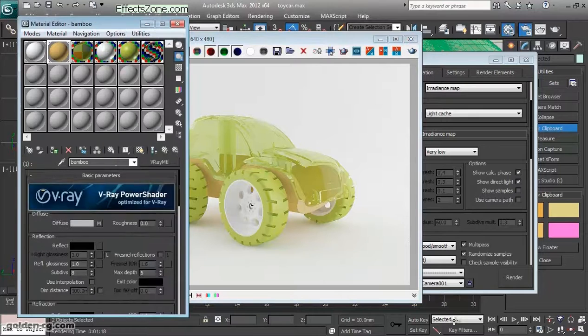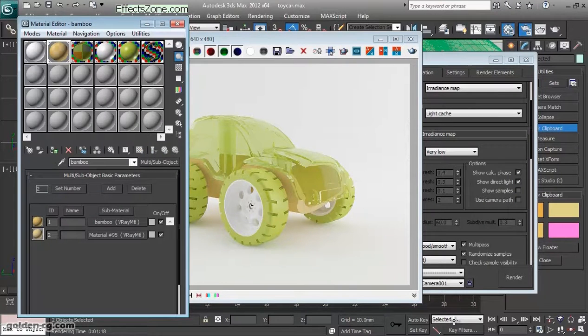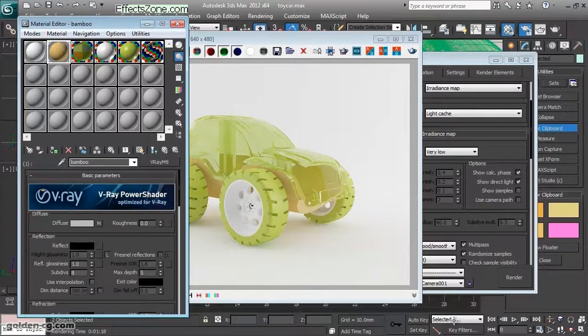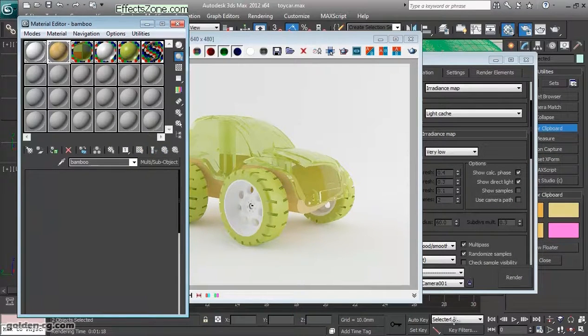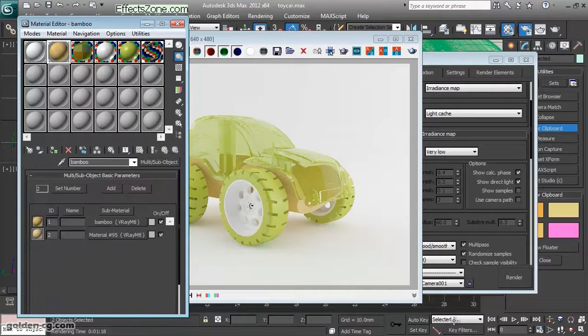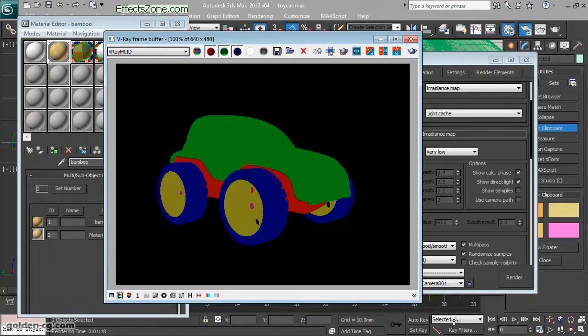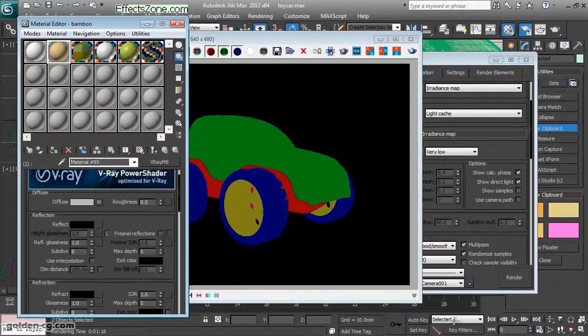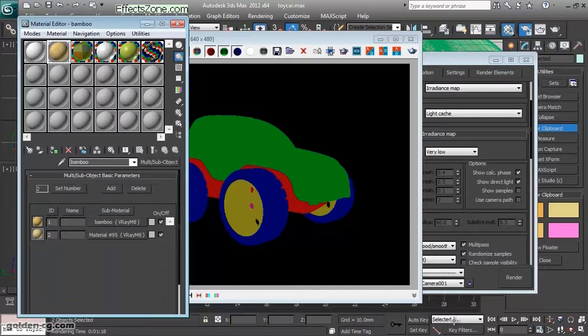And one note, I just changed it to 1, and actually all of these sub materials should also be changed to 1. That makes this V-Ray material for the wood, for both material ID 1 and 2, the red color. So I choose again 1 and 1, or I can even choose another number.